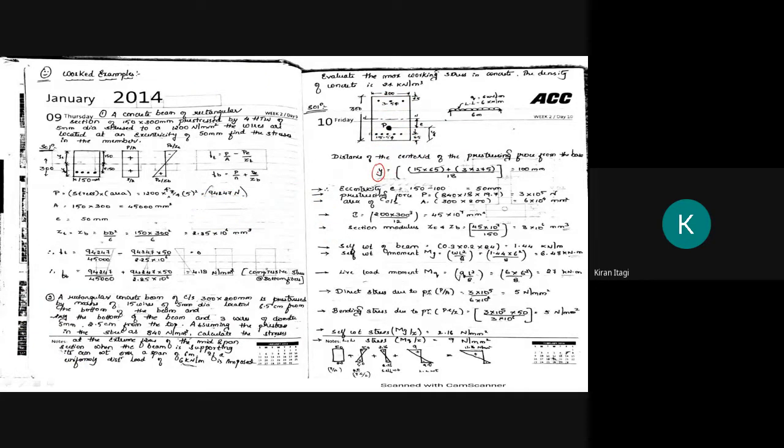Therefore, how do you determine that CG? That is y equals, first we take the bottom: 15 numbers of bars, what is the distance? It is 65, plus 3 bars, and what is the distance? You can take either from the bottom or from the top. So I'm drawing my reference axis like this. In engineering mechanics you have already learned this, drawing the reference axis at the soffit of the beam. From here to here it is 65, and from here to here it is 300 minus 25, that is 275. And how many bars are there? 18 bars. Therefore we have got the CG as 100. So the effective pre-stressing force is acting at this point.